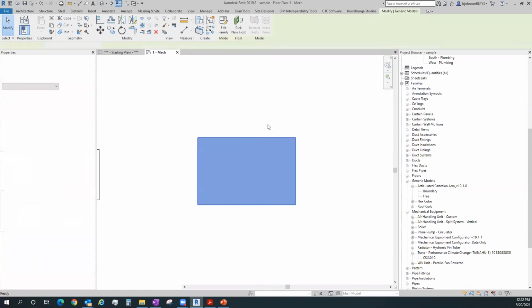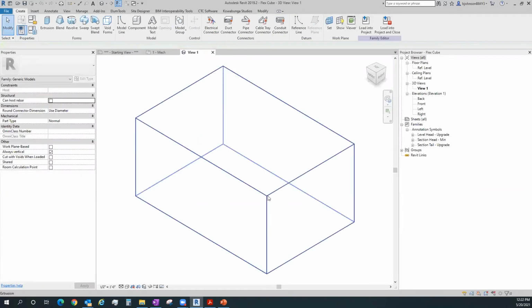So again, if I were to go edit family, because I have the placeholder family, I could just leave it in the model as like an LOD 100 with a couple of connectors on it. And as long as I had a cut sheet and said this was actually supposed to be 3 foot 3 inches and 3 3/8 inches or something, I could type in those values. It's going to stretch to that length. And then when I put my connector on it, if it was a pump, centrifugal pump or something like that, and it had an odd shape, I'm still getting at least my boundary, and it will clash detect in Navisworks or something like that.